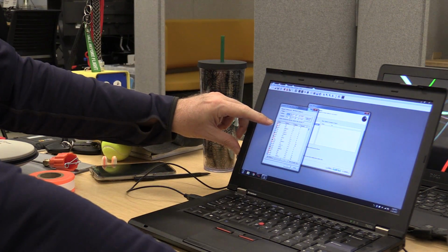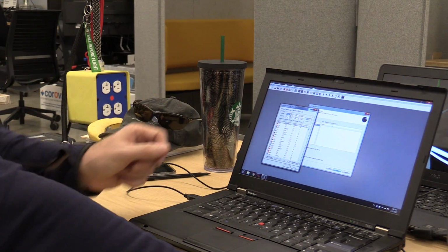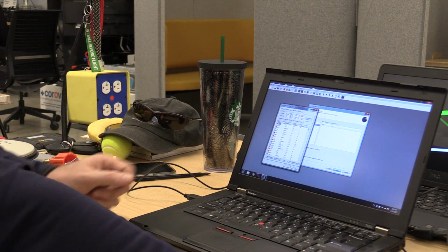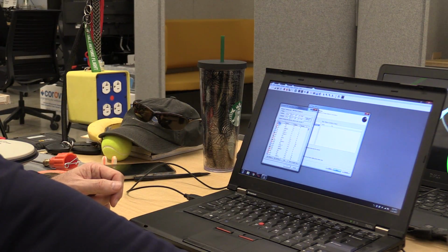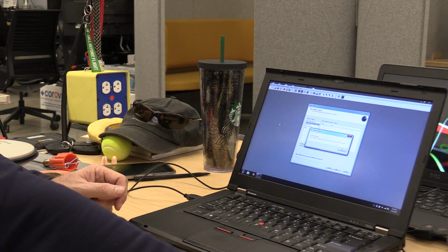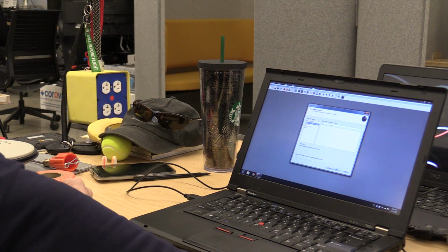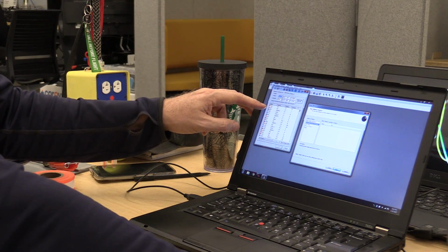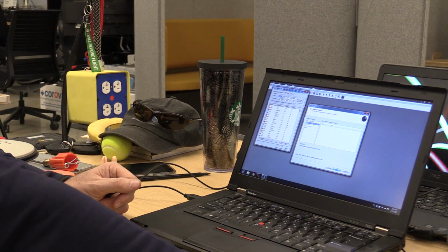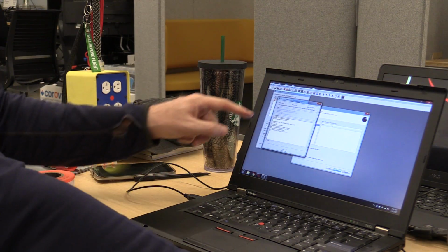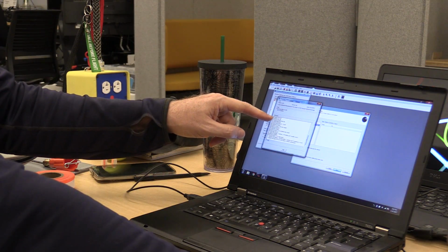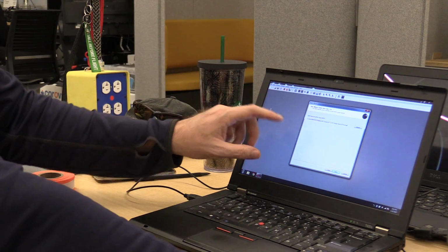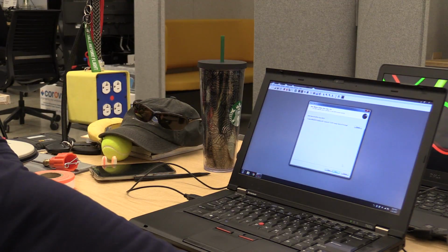I'm going to go ahead and pick the closest station to me, which is this SUAA. I double click that. Download failed. All right, so I'm going to pick the next closest one to me, which is 8 miles away. Then I should see a bunch of activity happening here, and all of the error correction data should be provided. If that's successful, then it's going to take me to the next step.